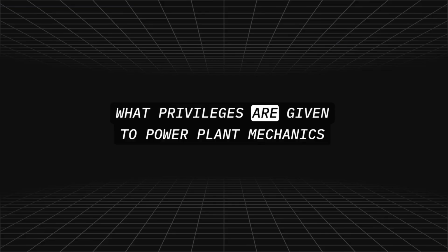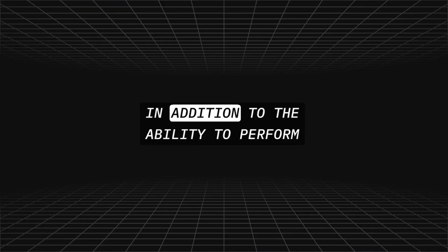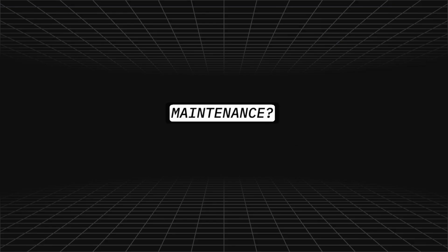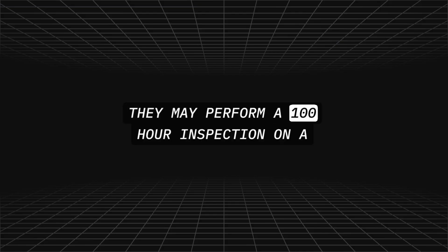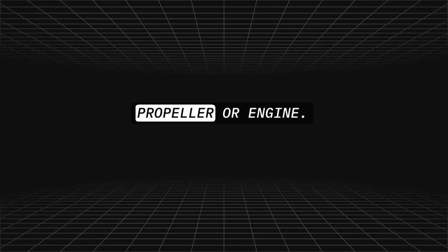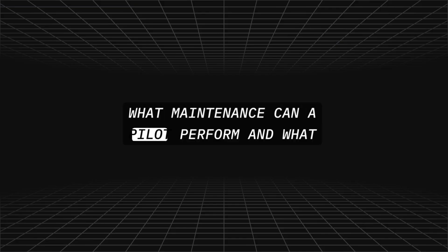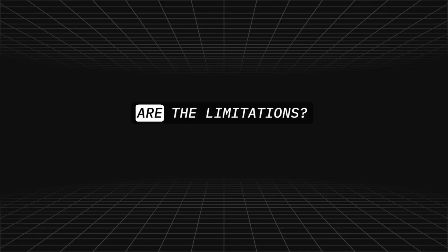What privileges are given to powerplant mechanics in addition to the ability to perform maintenance? They may perform a 100-hour inspection on a propeller or engine. What maintenance can a pilot perform, and what are the limitations?